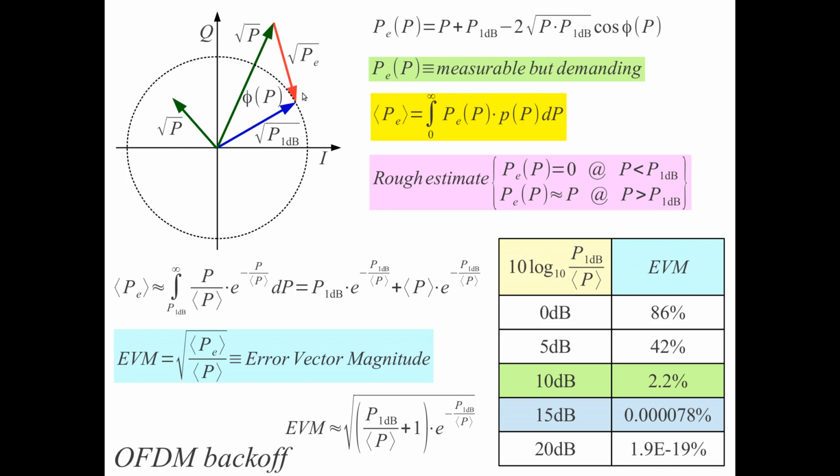Even driving it into saturation, the amplifier is no longer able to supply this power, and we cannot do any digital predistortion, just digital magic, to supply analog power at the output. So this is a really analog limitation. We can control the distortion inside the circle, and we can keep it arbitrarily small. But outside the circle, the best we can do is get to the dotted line here, the perimeter of this circle, with the generated output power.